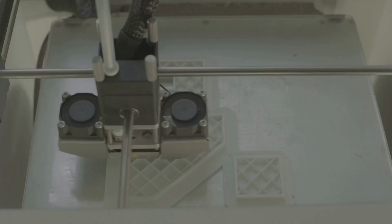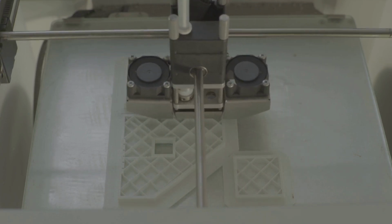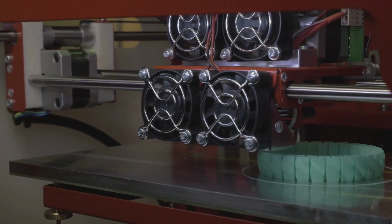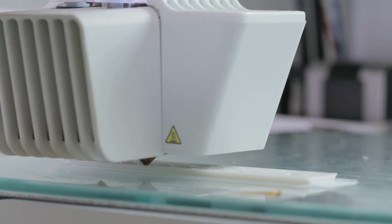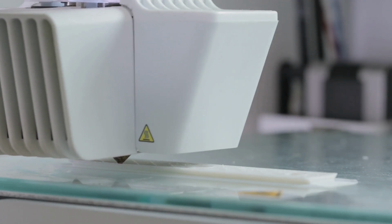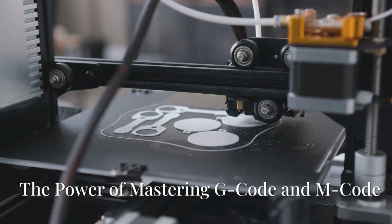Test and iterate. Don't be afraid to experiment with different G-code settings to find what works best for your printer and filament. Print test cubes or other small objects to fine-tune your parameters. By following these tips, you can write cleaner, more efficient G-code that results in faster prints and higher quality results.